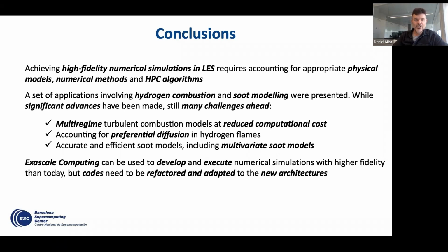high pressure conditions. Then if we want to correctly reproduce the flame propagation, we need to include preferential diffusion in our simulations. And the same for the soot. We need to incorporate multivariate soot models so we can consider a more realistic description of the physical phenomena of soot formation.